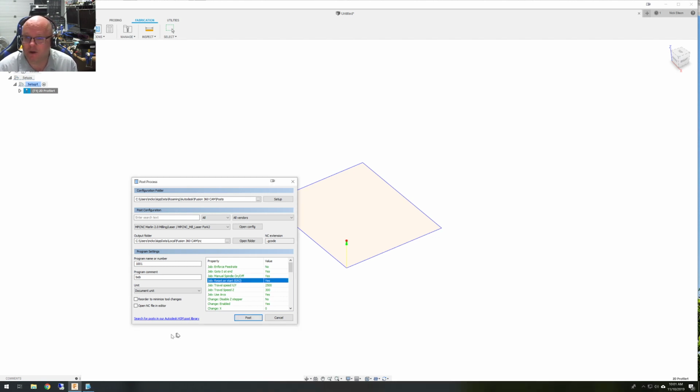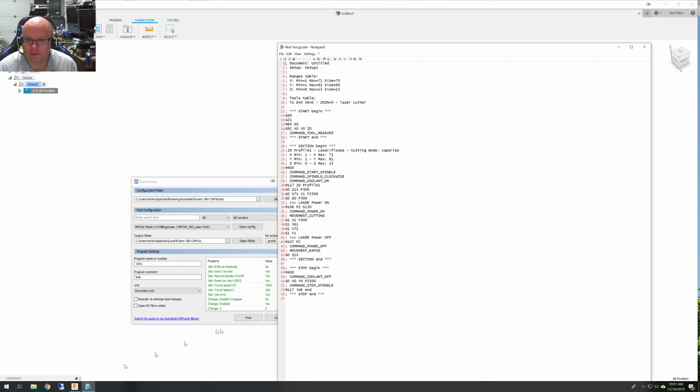So if I look at my G code, it actually puts the G92 X0Y0Z0 to say, hey, wherever you're currently at, that's your new 0. So you can have it not put this command in there if you want absolutes. And this is where you would set it in the properties of the post processor.